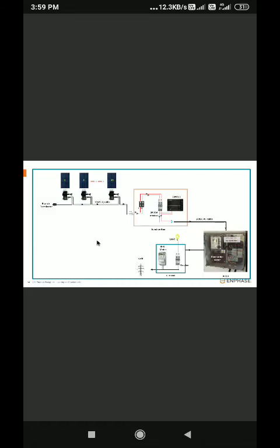It has an AC bus cable. Okay, this is flexible. It directly parallels all the inverters. You can then use this cable to connect to each inverter as per the string sizing. And at one end, we use the branch terminator to end the cable, and then directly you terminate it to a roof isolator.